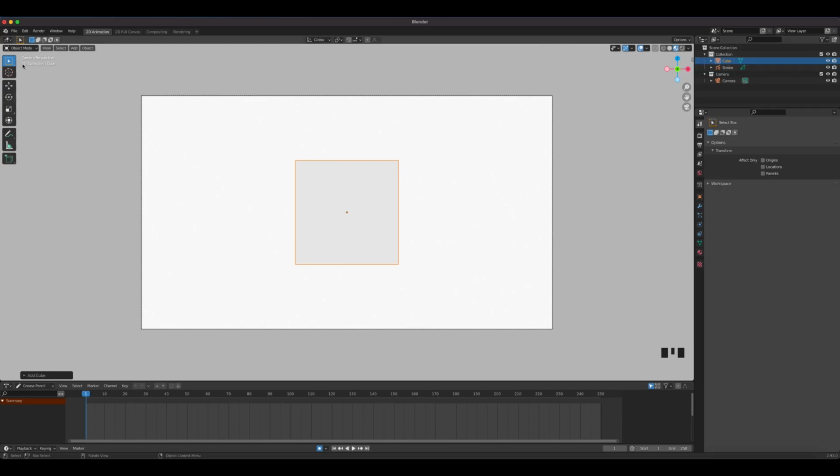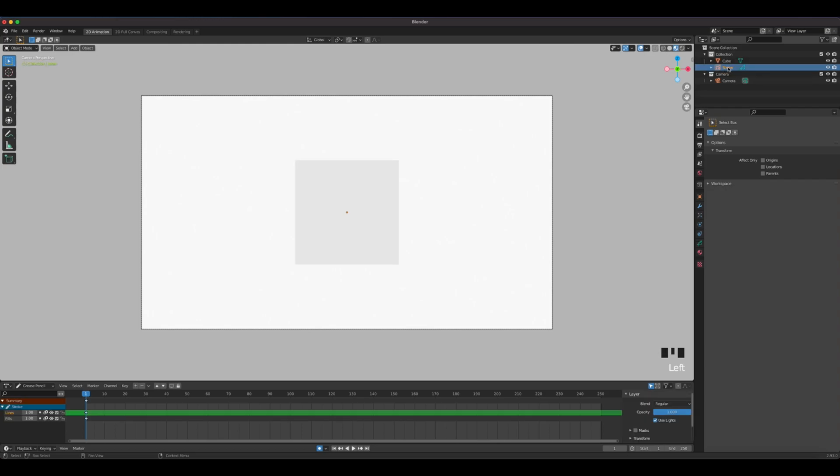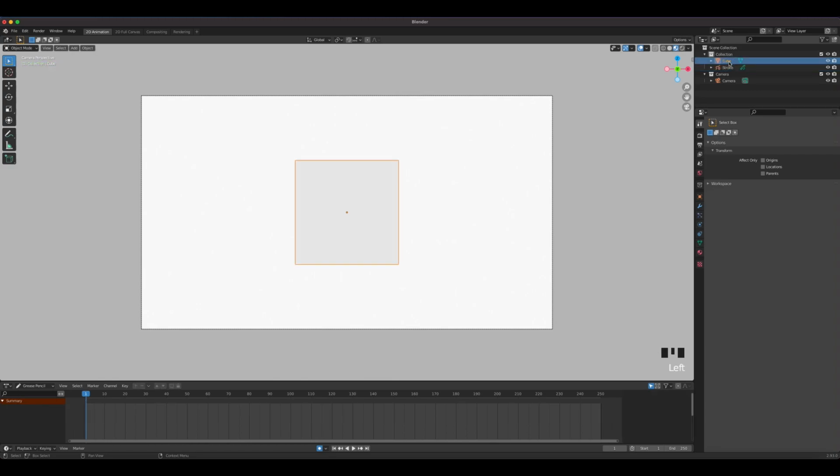So if I go to the drop down of object mode, as you can see, draw mode is missing, because I have a regular object selected. So only when you select stroke right here will you see draw mode. So remember that. If it's probably killing you that you can never go back to the draw mode, it's probably because you don't have a grease pencil object selected. Okay, so let me select cube right there, press delete, get rid of it.